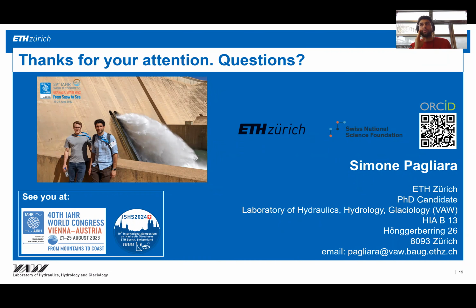In my model, we have acrylic glass walls, so to investigate the flow attached to the wall, yes, you could potentially use them, but you cannot at all penetrate with PIV to the core of the flow because of the high turbulence levels and aeration.